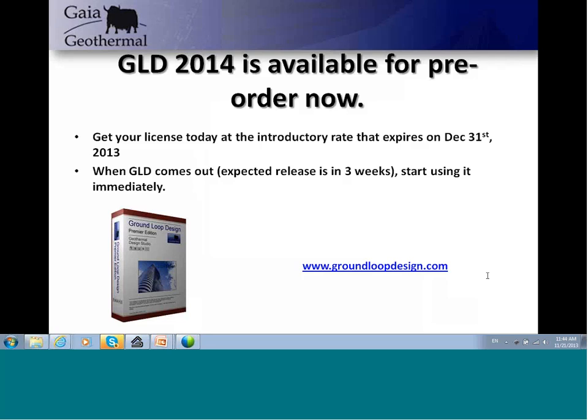The TRACE program does use hourly data, and there is a way to export hourly data from the TRACE program. So certainly if you use TRACE, you can get the hourly data. If you use the Carrier HAP hourly analysis program, you can get the data. If you use EQUEST, those are energy simulations based on hourly or shorter time steps. They all have access to this data that we can use inside of GLD. That's one question.